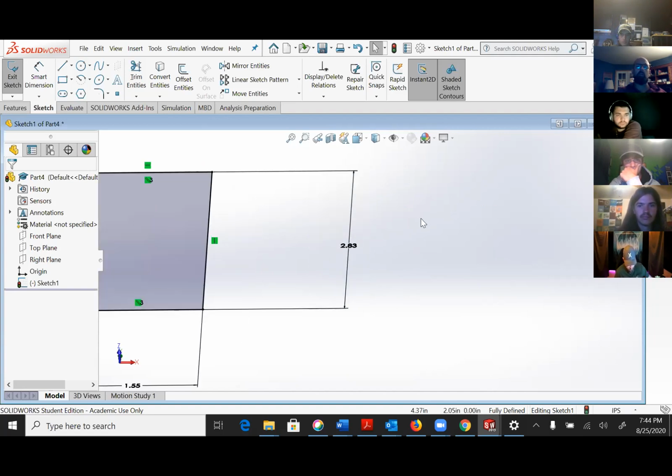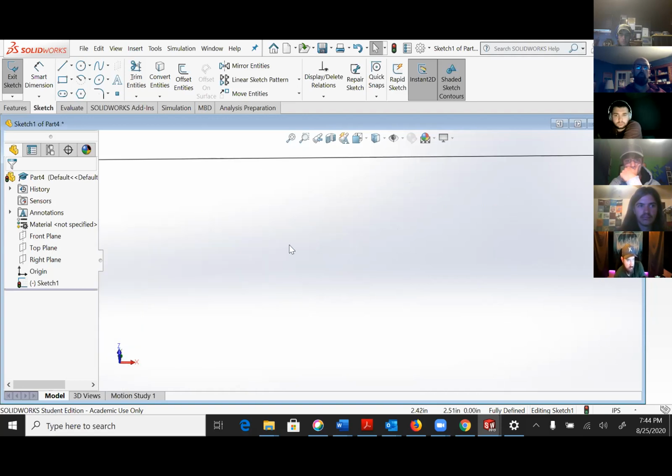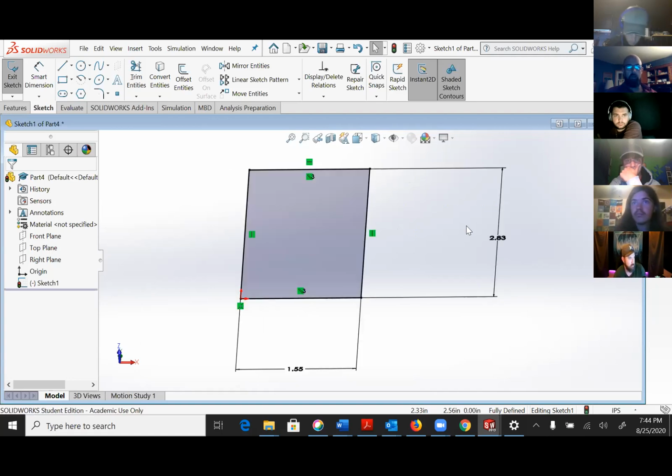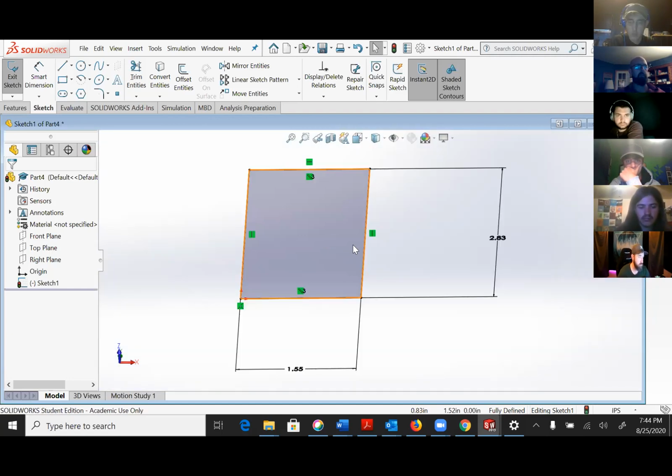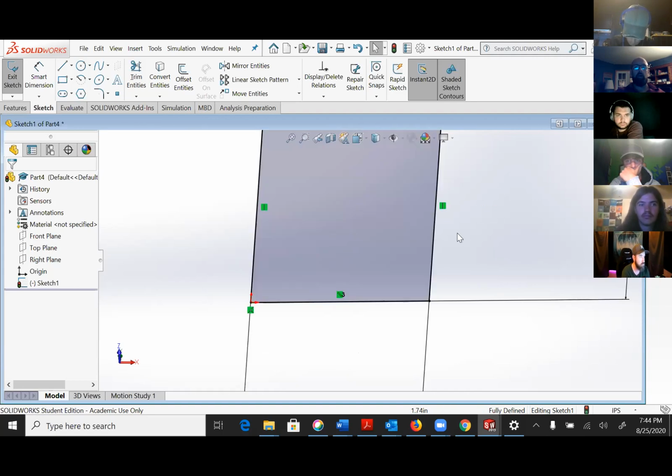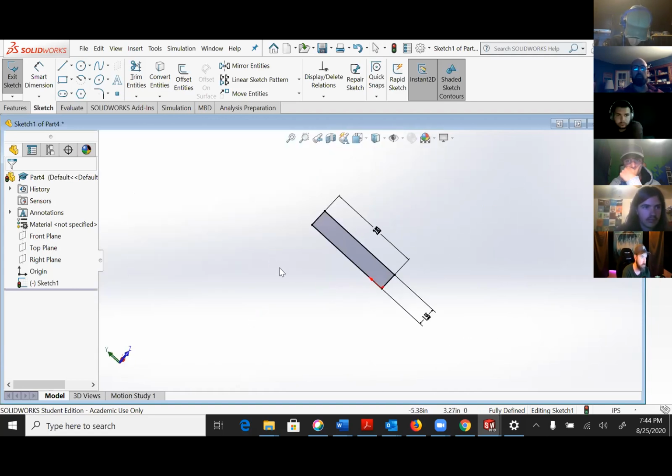Here's, try this, watch this. I'm going to zoom, whoa. Oh crap, I'm in space, I'm rolling the mouse, I can't find my part, it's somewhere out there. I'm going to hit the F key as in Frank. And that fits it to the screen. Here I'm zoomed in really tight, F. Okay. And often you will lose your part. It'll be somewhere in outer space, F.